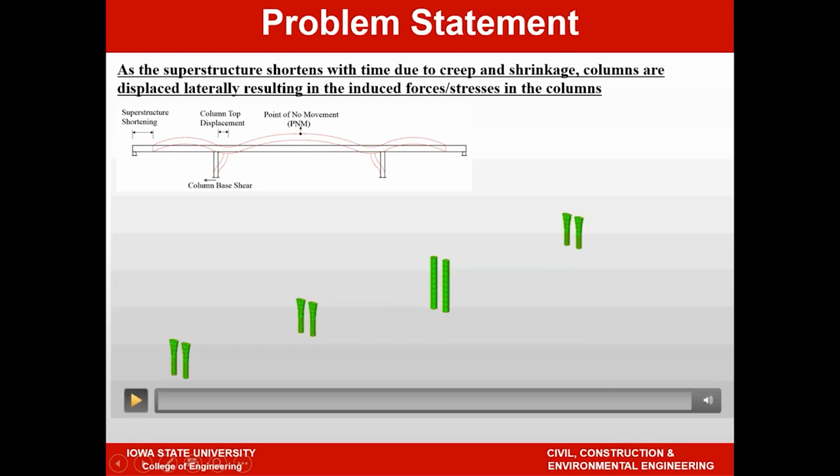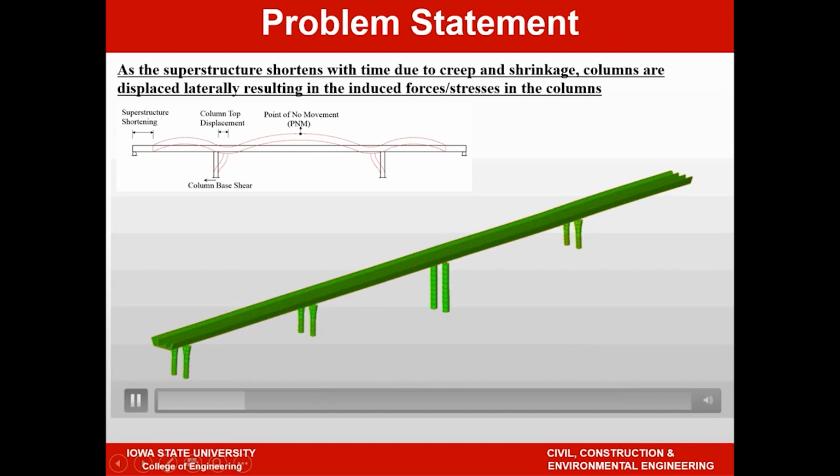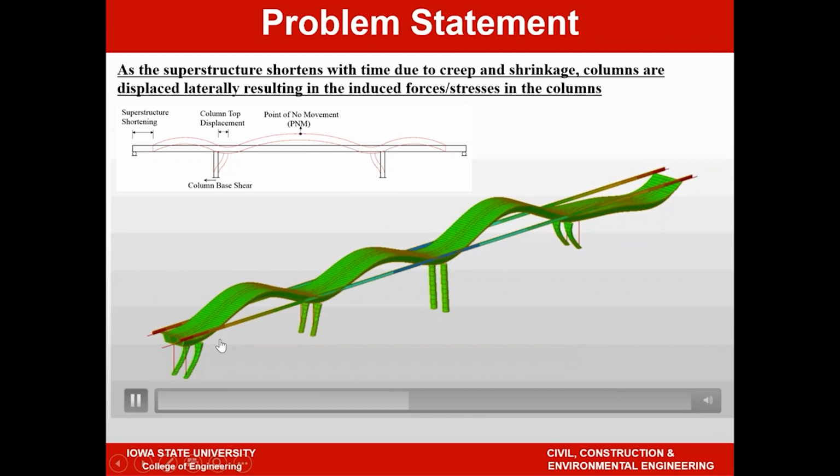Let me show you a video of a frame that we built in MIDAS Civil, and that shows a multi-span frame. Typically, the construction of the substructure first takes place, and then you add the superstructure, introduce pre-stressing, and then the time-dependent effects will continue to take place, which is something you can see in terms of how they deform. So the point to